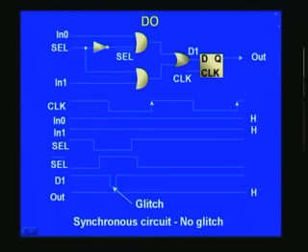The way to do it is to put the flip flop here. What happens if there is a flip flop here? Naturally you can rest assured that there are other flip flops from which other signals are coming, or it may even be asynchronous, in which case you cannot directly put it here, you need another flip flop and then only process other asynchronous inputs, which we will see in the later slides. And here, all this glitch will happen before the rising edge of the pulse.